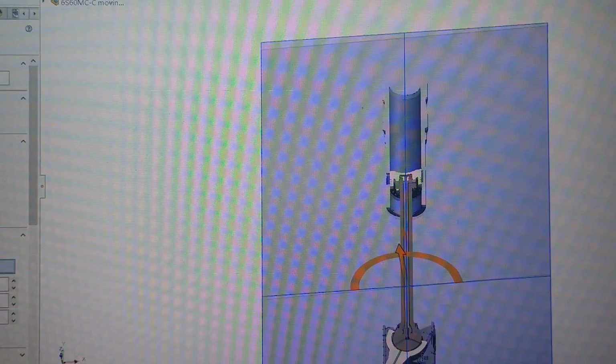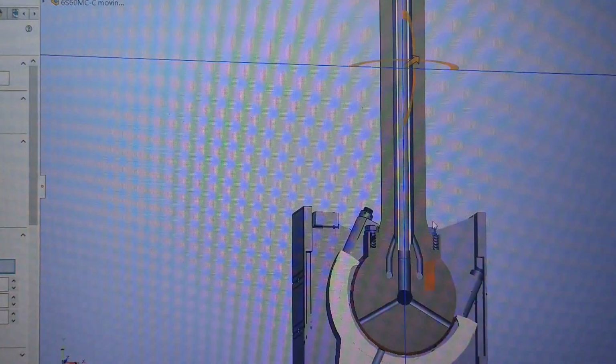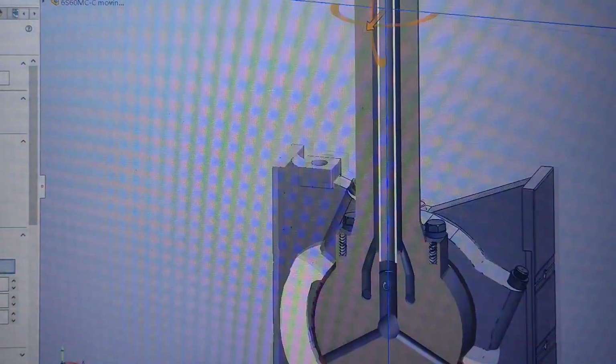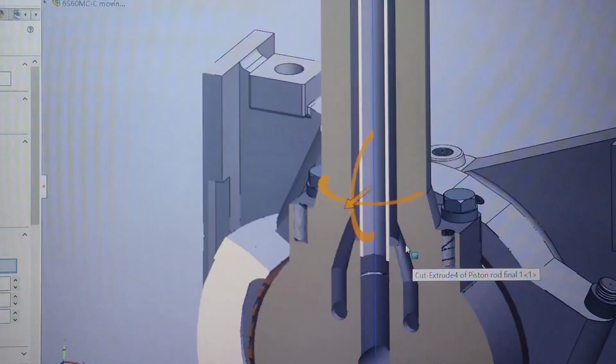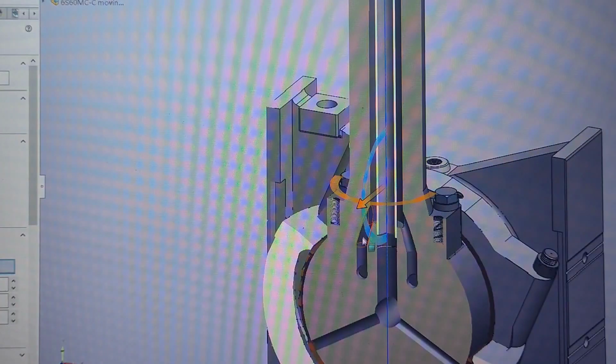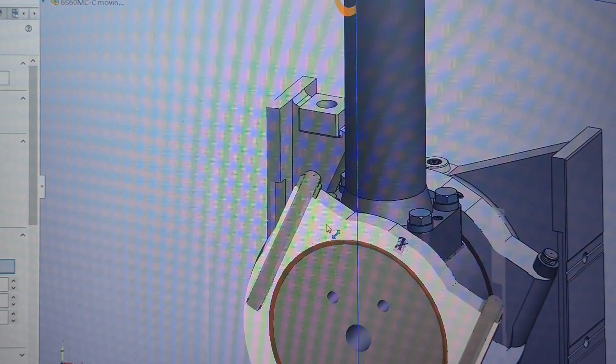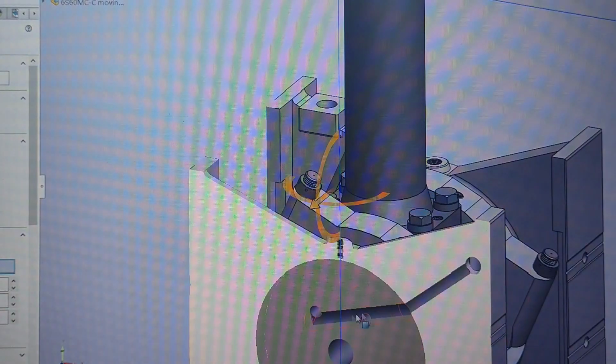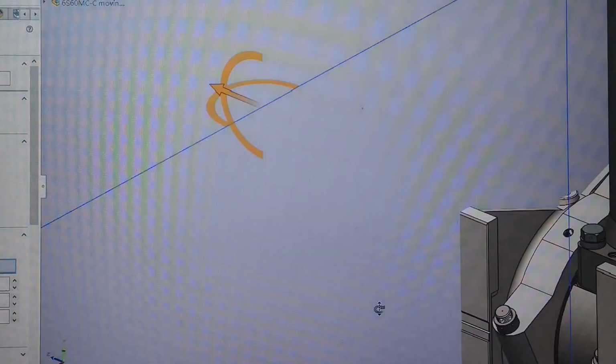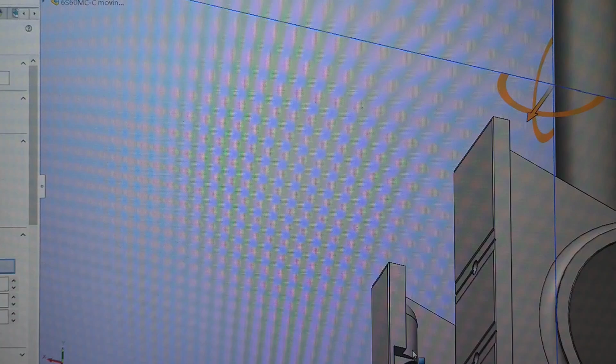So that part of the oil is used as a coolant for the piston head, and the heated oil will be delivered to these two holes in the crosshead pin. They will flow until they reach here and go to another crosshead plate and be going to here.